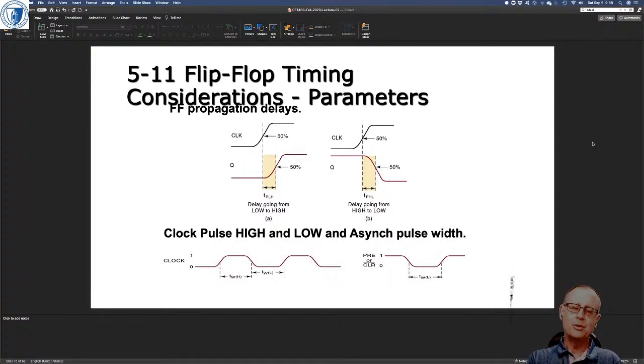Even if you've got the best system possible, there's still going to be a little bit of capacitance or a little bit of inductance hanging around. So you get I equals C dV/dt. If you have a completely abrupt change in voltage, dV/dt, the derivative of the voltage, is going to be very big, so you're going to get a current spike.